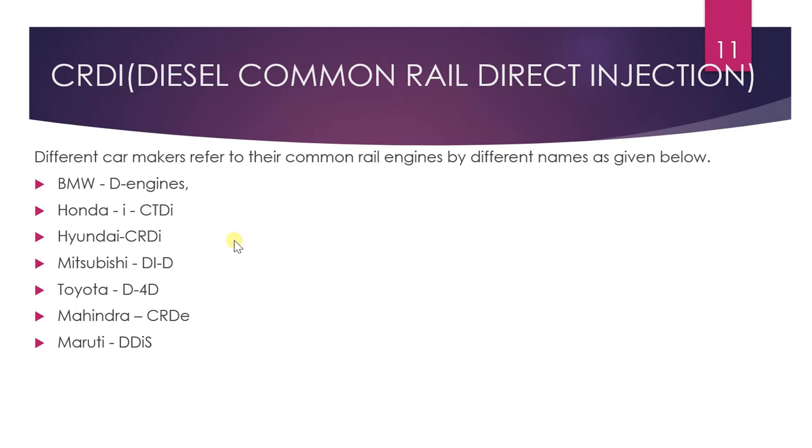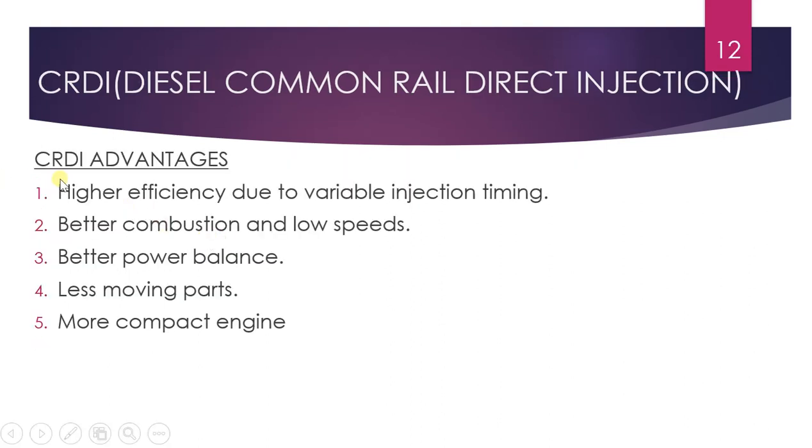And next is an important one, the advantages. What are the advantages of a CRDI? The first one is the higher efficiency and the variable timing of this fuel injection system, and because of that the efficiency will be higher in CRDI systems, with better combustion at low speeds.